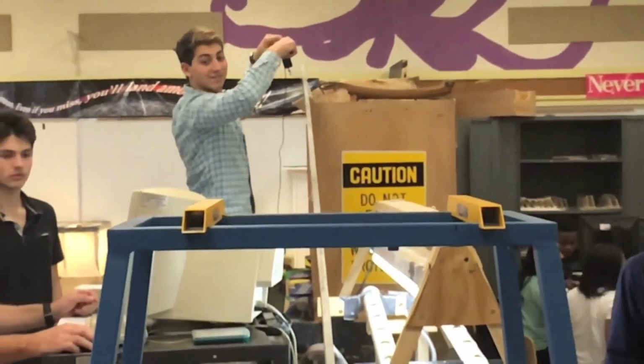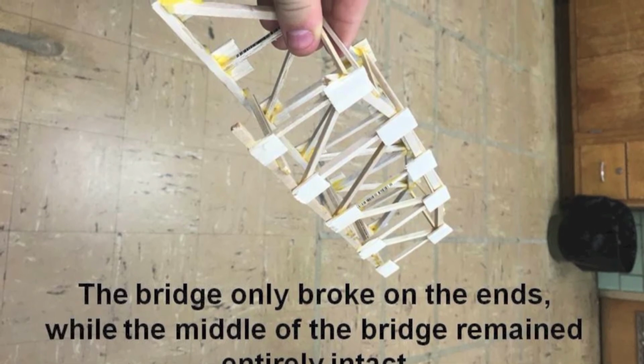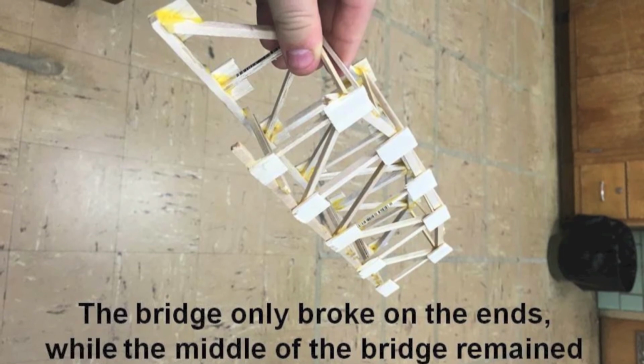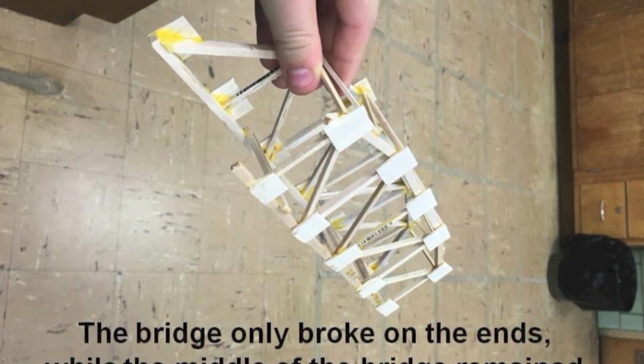That was great. The break in my bridge was ideal. It did not break in the center, meaning it survived the forces of tension and compression. However, the bridge had breaks on the ends, meaning shear force was the reason for those tiny breaks.